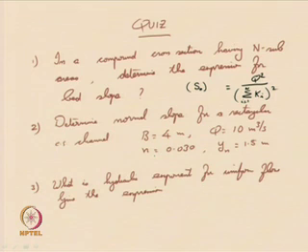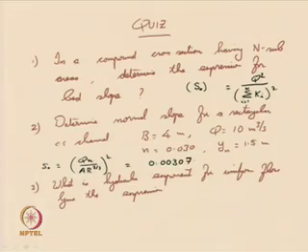The solution for the second question is given as S naught is equal to (Q n by A R to the power of 2 by 3) whole square. On evaluating the quantities, I get the value as 0.030. So, please verify it. If there is anything wrong, please let me know.